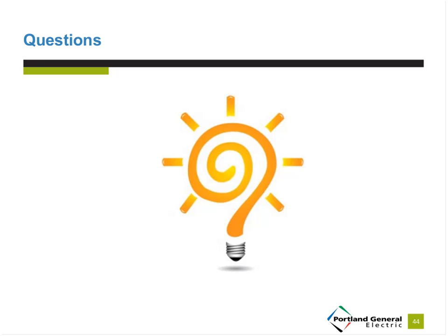No, don't do that. And I've seen that before. I've been out to businesses before. They have T8s, and then they've got one. They actually have all T12s, and then they've got one new one, but they've put T8 bulbs in the T12 fixture, and that is just going to make the bulb burn out. So you have to be a licensed electrician to do the work officially, to get the Energy Trust incentives to do that. So yeah, you need an electrician to change the technology of the magnetic ballast to the electronic ballast.